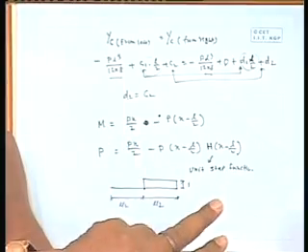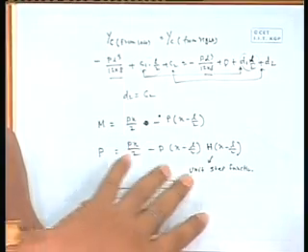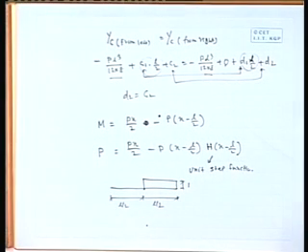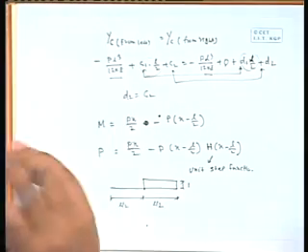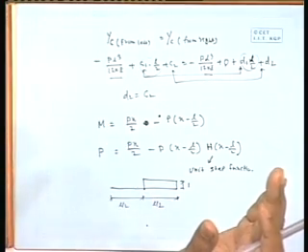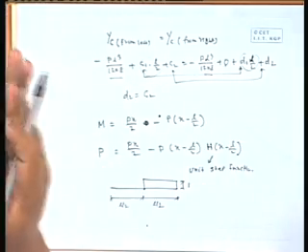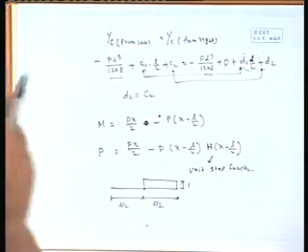When it is after that load, this plus this quantity. So, that physical logic we are trying to put in a mathematical form with some function called unit step function. So, it will give a general expression for bending moment for the entire span, because both the sections' constants will be identical. I think we can stop here at this class.